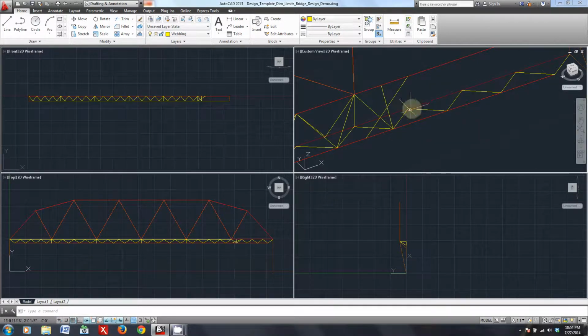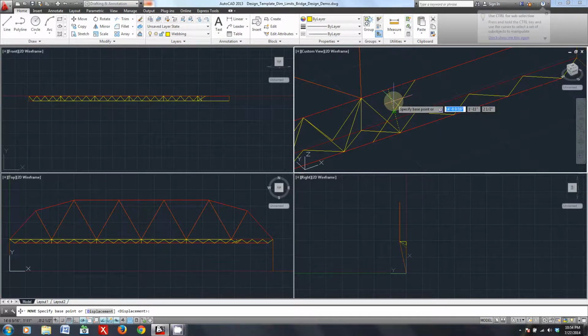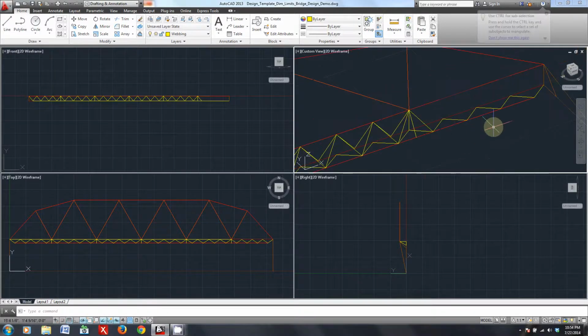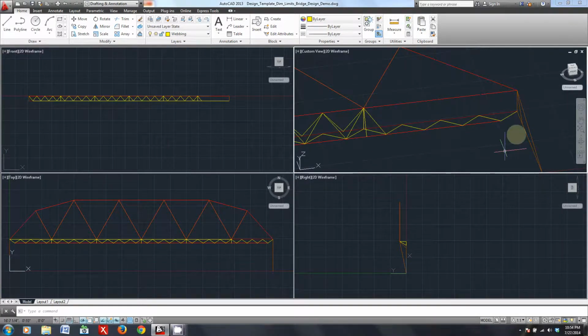Now, I already have these intermediate webbings placed there, so I could have just connected down there, but if you didn't have that place to start, then you can do this trick where you're using midpoints and then just sliding your webbings down to join up with the girder. And that's very useful if you're trying to very quickly flesh out some kind of simple webbing configuration.